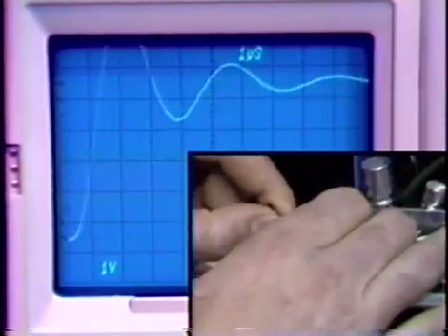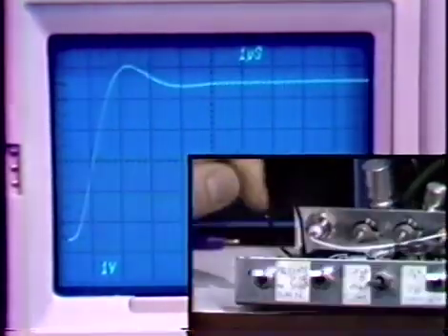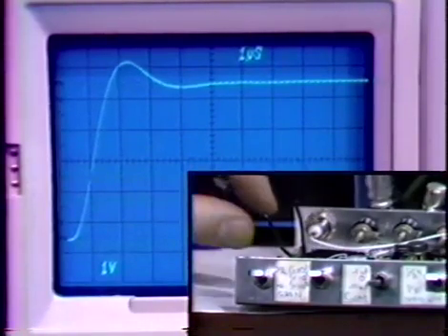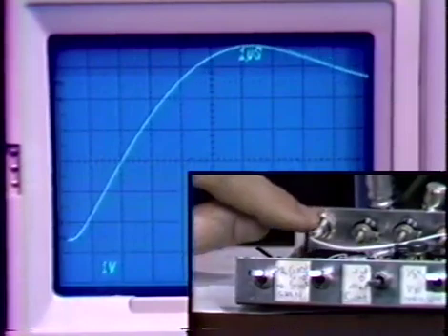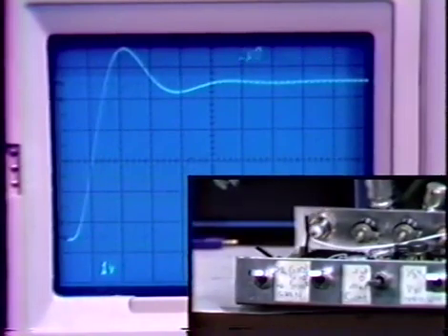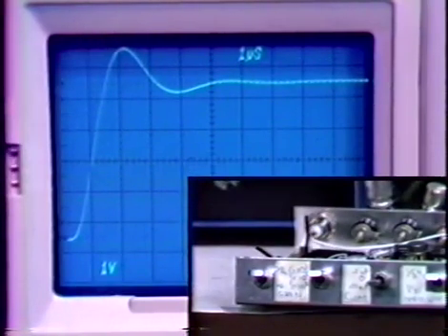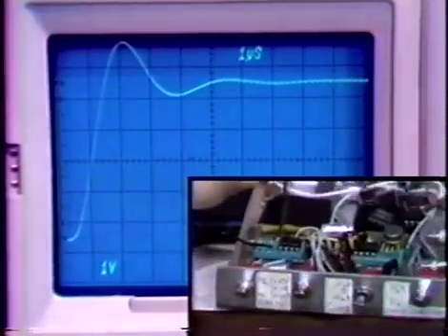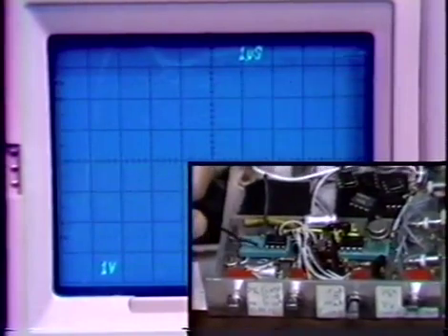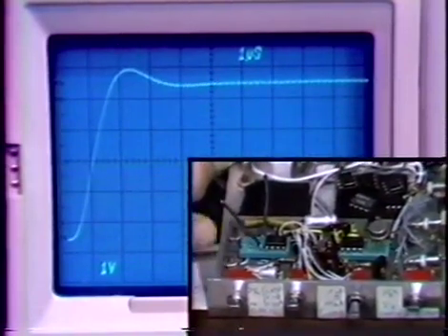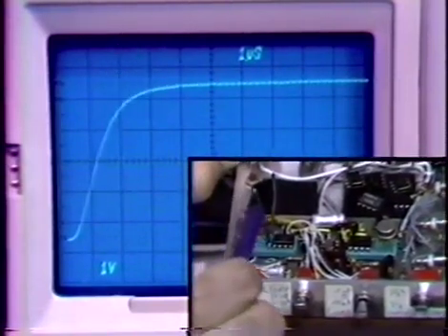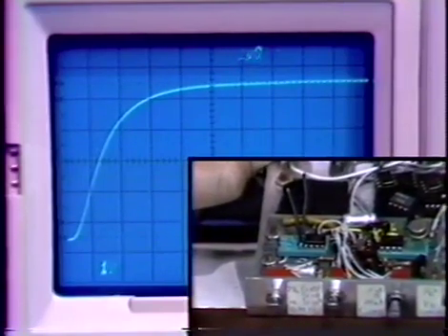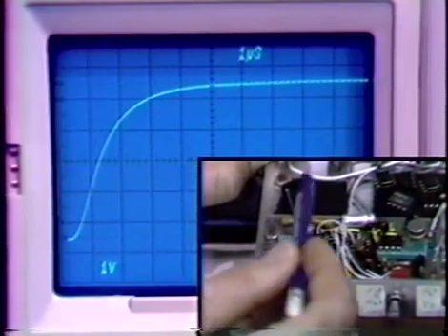And we now have a very convenient method for adjusting capacitance at very small values. If we get these apart, we have the undercompensated case with a reasonable amount of overshoot. As we move the 2 wires together, we're able to get progressively better damping. Here's a critically damped case, no overshoot. The closed loop poles appear to all be on the real axis.